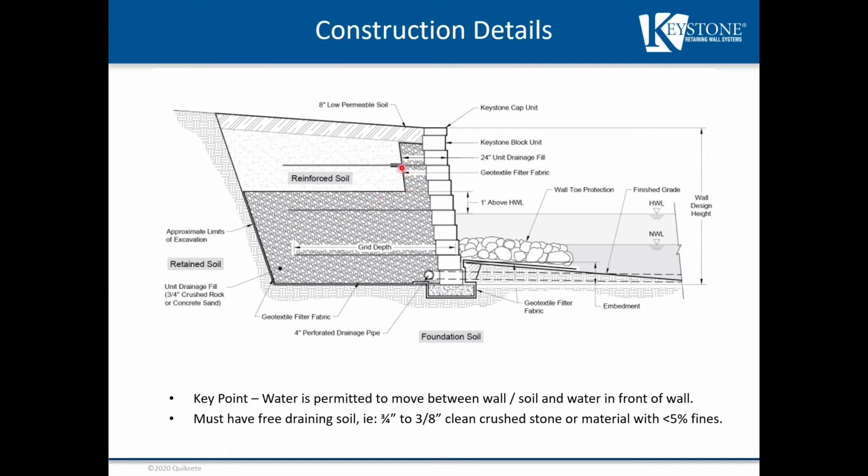And finally, we're going to have our final wrap up here to keep our free draining material or drainage zone aggregate, as we've shown in previous tech talks, for our walls. This is more of a standard application, but we want to continue that fabric wrap all the way to the top of the wall, just in our free draining zone behind the wall there.